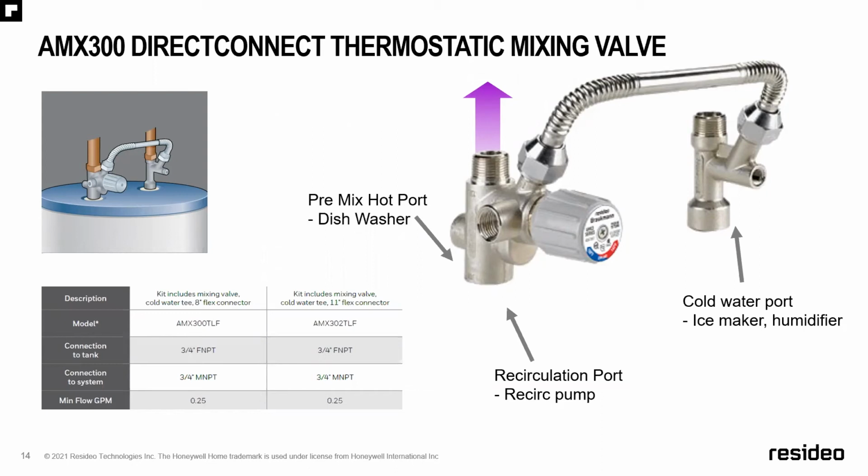This does have a recirculation port. However, I would recommend making sure that the flow rate of your recirc system fits this port. The flow rate on this recirc port is pretty low because it's tight spaces in there. So just make sure that if you are using that for a recirc system, it's going to fit the right application. And if not, we do have an alternative, and I'll talk about that in the next slide.